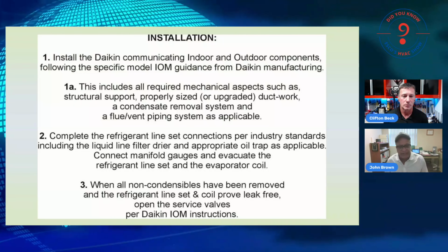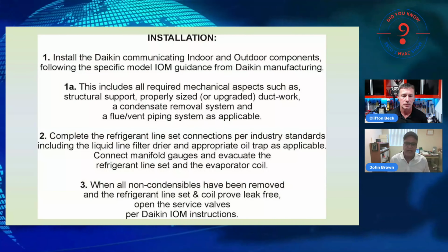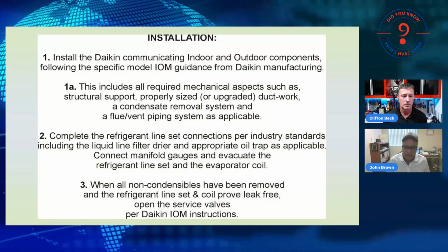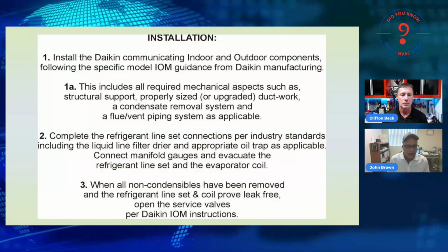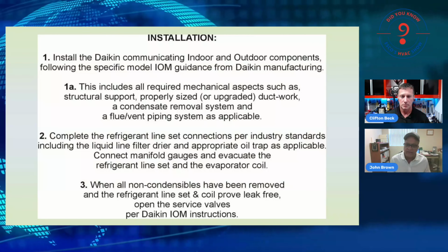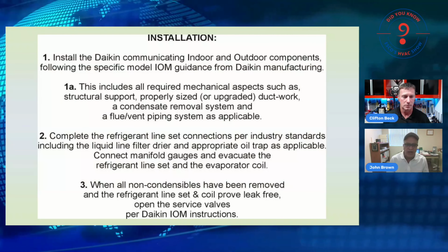Connect your manifold gauges, evacuate the line set and the evaporator coil. When all the non-condensables have been removed, and the line set and the coil are leak free, open the service valve per Daikin instructions.